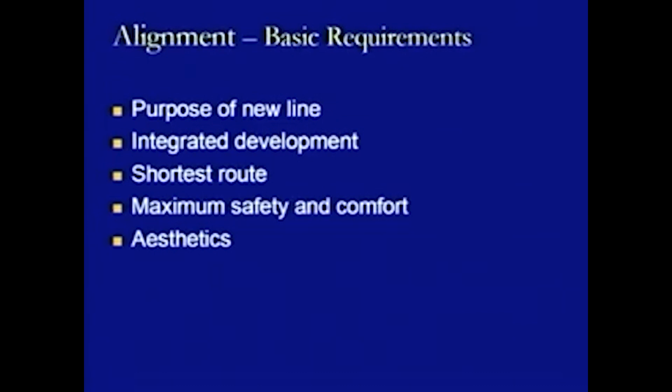These aspects which need to be taken into consideration may also relate to safety, which is another point. As we talk about the hilly area, it is not at all possible to connect the point at the top of the hill directly with the point at the foot of the hill. What we do in those cases, so as to maintain the safety of the rolling stock, is provide a circuitous route which moves maybe along the side of the mountain, and that is how the distance has been increased, but the safety is being maintained.